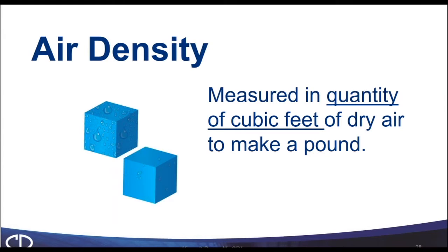Enthalpy is used to help you determine how much heating and or cooling we are doing. We noticed that enthalpy was so many BTUs per pound of dry air. So how can we know how many pounds of dry air we have? Let's discuss air density. It's going to be measured in quantity of cubic feet to make up a pound. How many cubic feet does it take to make up 1 pound?